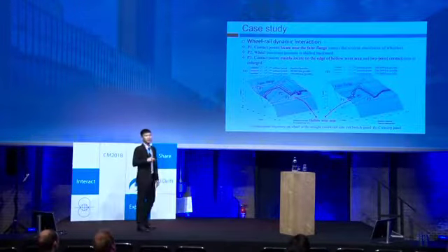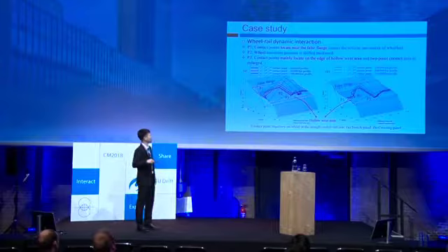But on the contrary, when the operation mileage is above 200,000 kilometers, the wheel set will move in the opposite direction laterally in the switch panel. We will discuss this later in a little more detail as we go on. Okay. And this figure shows the contact point trajectory on the wheel at the straight switch rail side.